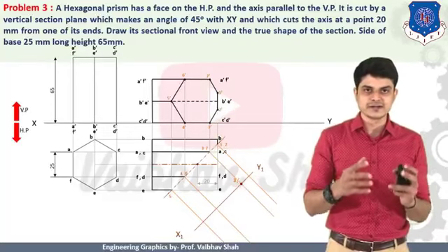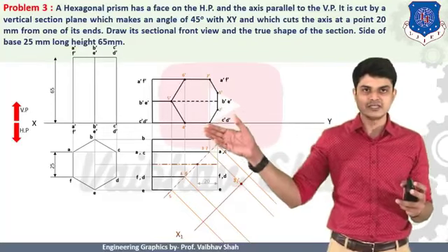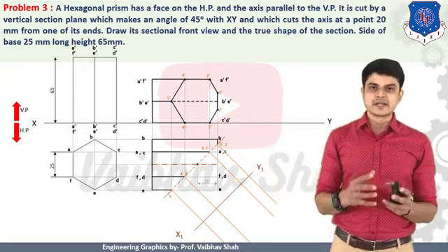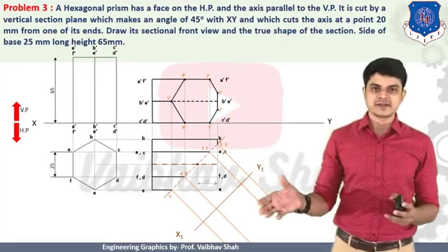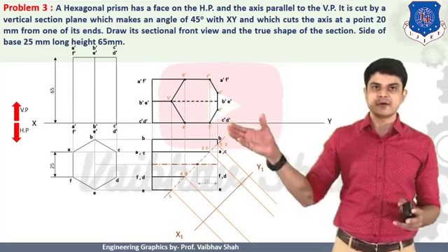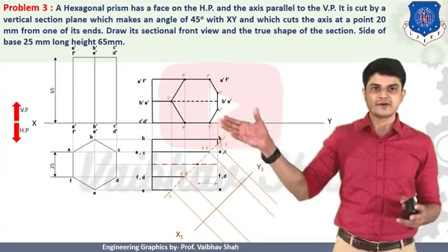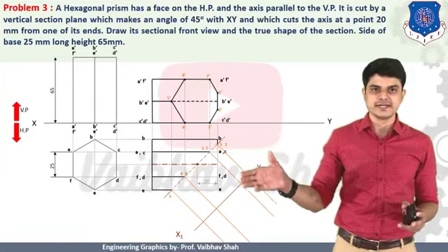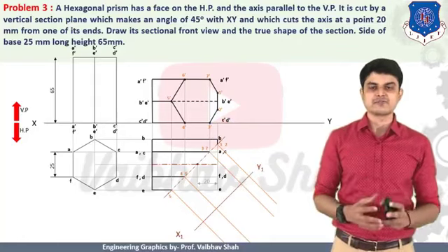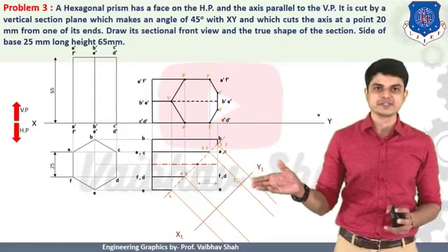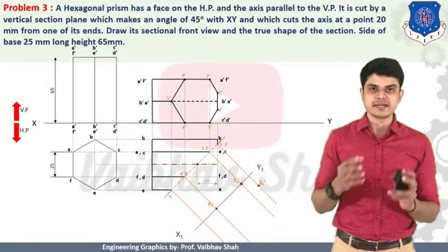So you should transfer each and every point with respect to the XY line here. Now let us start transferring the points with respect to this XY line. We can see that there are 3 dash and 4 dash points on the XY line itself. So we should put the 3 dash and 4 dash points onto this X1 Y1 line respectively.